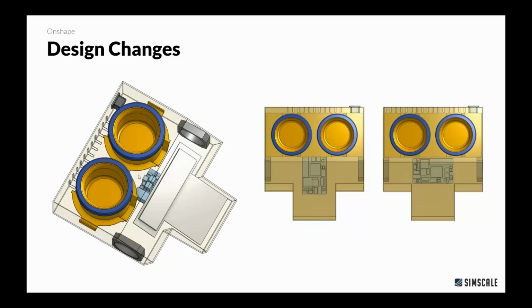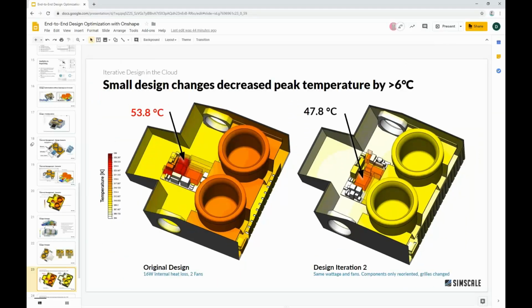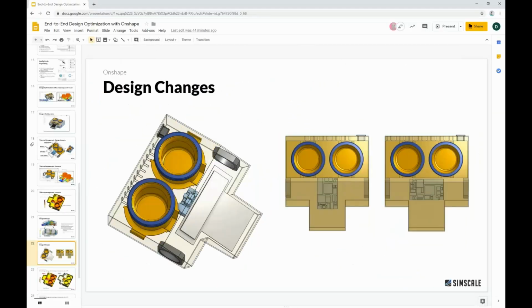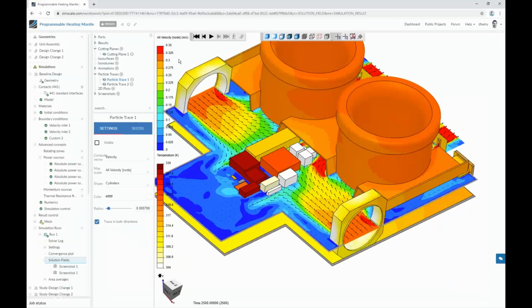Yeah, the idea here was because we saw that there's a lot of air moving through under that sheet metal part, but not enough over there, right? And so to even that out, we did test these cutouts. And a second change was, instead of actually redesigning the board and thinking about board placements, just reorienting the board, right? So, no harm done. That doesn't change cost, that doesn't change the fans, that doesn't change anything. It was a spoiler now, but I assume you know where this is going, right?